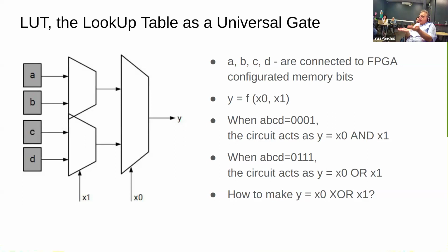In FPGA, you can compensate for its problem with clock frequency with a high level of parallelism, because with a microcontroller you have a program which simply goes instruction by instruction, but with FPGA you just do many processing in parallel, and as a result you can substitute frequency with parallelism.